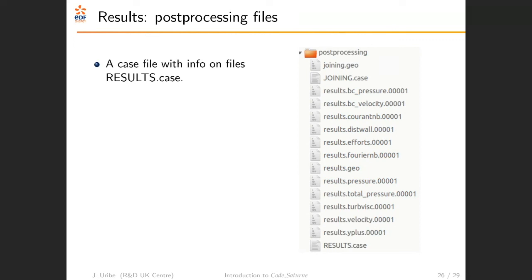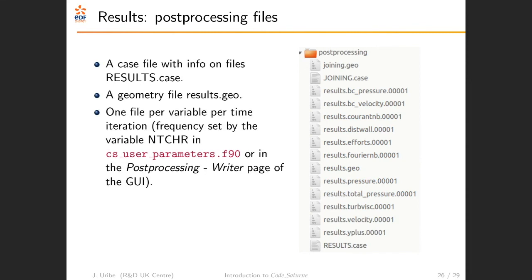So the post-processing file is the one that is going to read the geometric file, and then the variables that you want, depending on your setup. You can change the frequency of how often the variables are written, so every n number of seconds or every n number of iterations, so that you can see the evolution in Paraview as well.